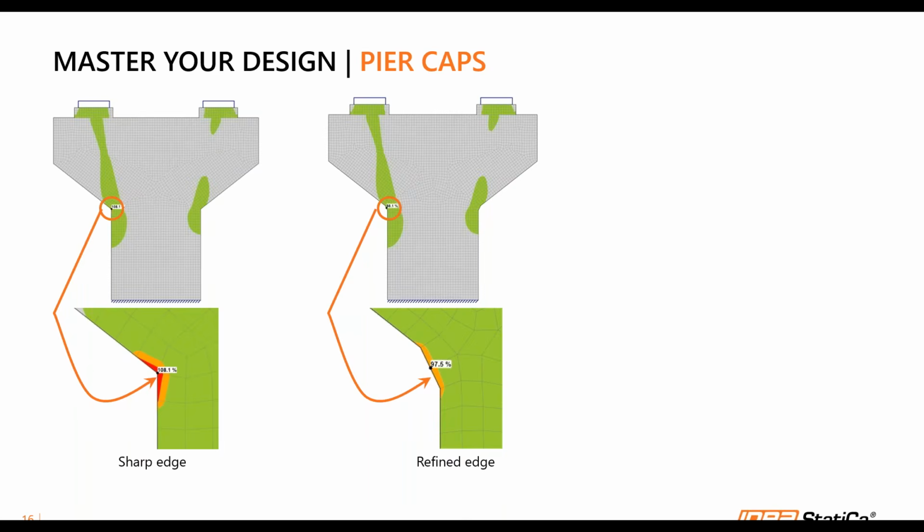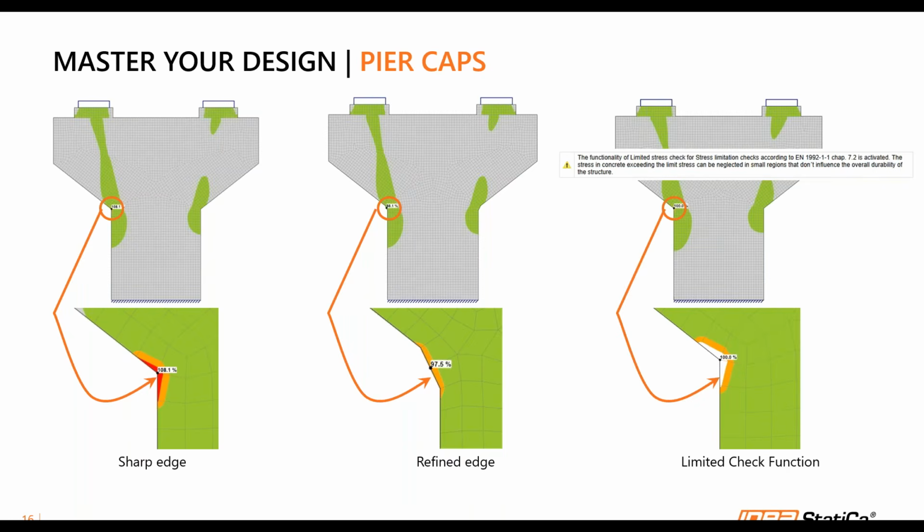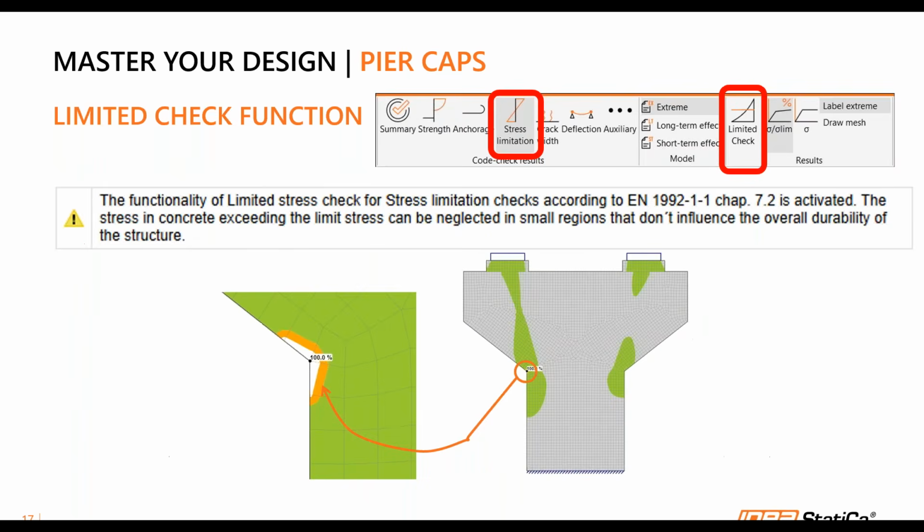The other tools that we have in IDEA StatiCa is to make use of the limited function check. With this one, you can activate these functions as long as you know that these stress peaks do not affect or influence the overall stability of the structure.